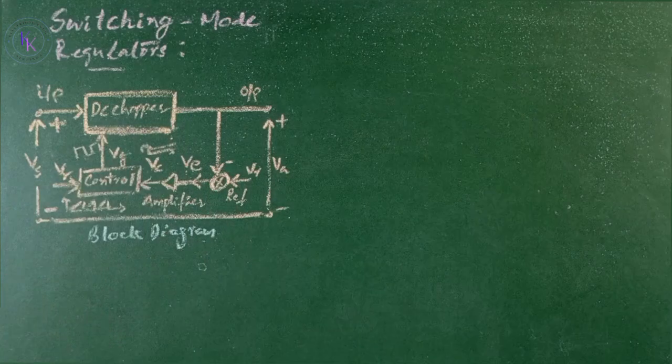DC chopper. We can notice in the topic of DC chopper with resistive load, the output is discontinuous and contains harmonics. The ripple content is normally reduced by LC filters. You can refer to the topic DC choppers with resistive load. The link is given in the description.